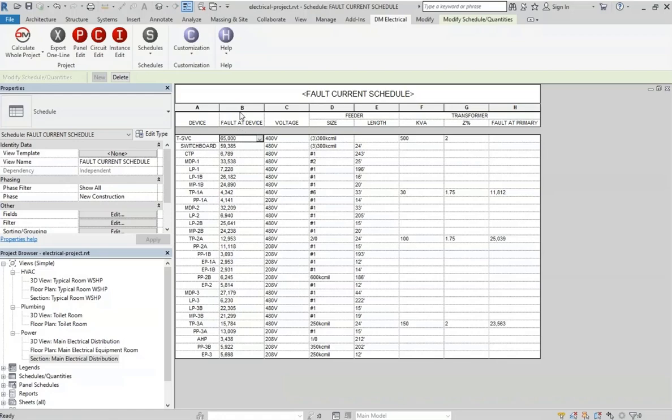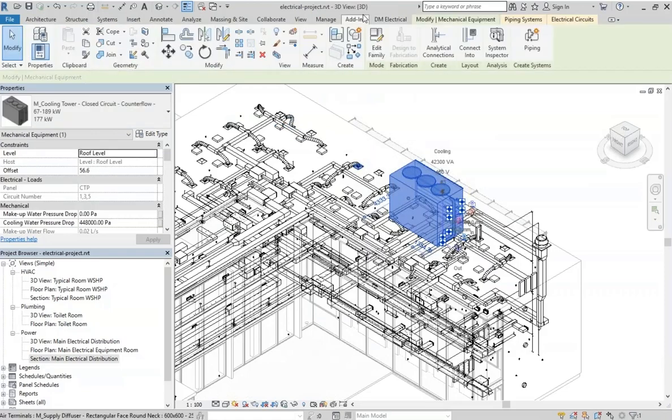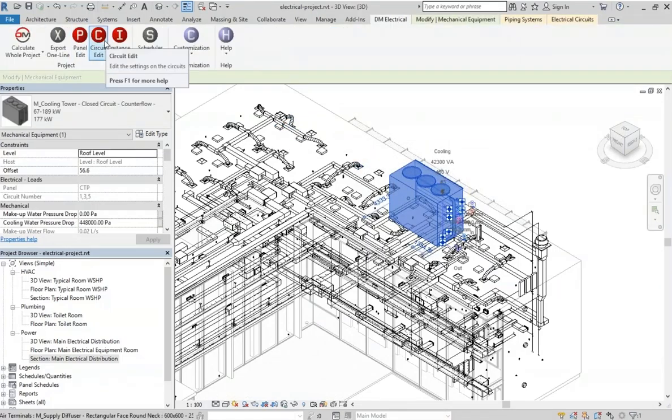The final big feature that we have, or set of features, is the branch circuit sizing in Revit. When Revit does its branch circuit sizing, you basically get 20 amp circuits everywhere. Our software overwrites that and actually attempts to size the circuits for you. And that's the overview of our software.